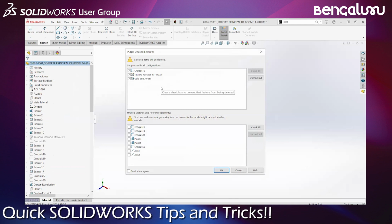The main use of purging unused features is, see if there are any unused features in any of the configurations. For example, assume that you have 5 or 6 configurations of the same part, and there is some feature which is suppressed in all the configurations, which means that feature is no more required. That's what it means, because if you have suppressed it in all the configurations, and there may be a few other sketches or any of these things which are not used. You might have created a plane, but that has not been used as a reference for any of the commands or any of the features, right? Then it is considered as unused. So SolidWorks quickly brings up all the items that you have either suppressed in all the configurations or which have never been used after being created.